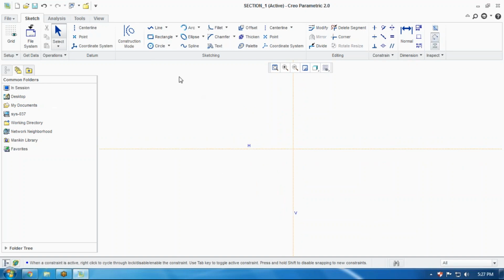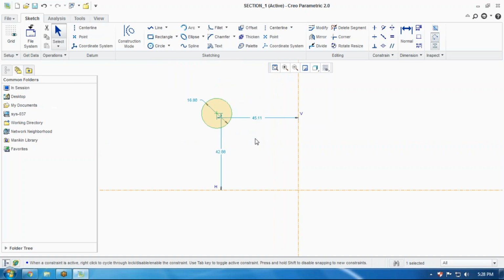After that I'm doing one thing here, click on this again, provide 1, that's 2. After that provide the line command or, if you want to create a circle, go for circle. You have to specify the center point first of all, so I'm specifying the center point here. What will happen, it is giving me three conditions. One is horizontal distance, then vertical distance, then radius or diameter. So here we need to double click on this. I'm showing one more thing. It shows me two colors of the dimensions. If this is light blue, it is a weak dimension.